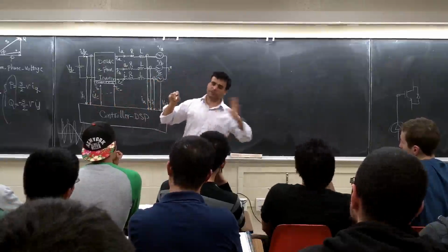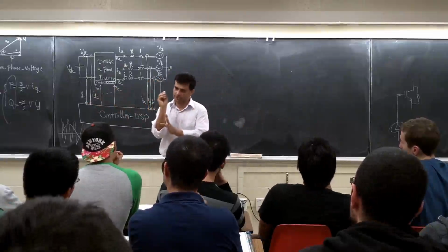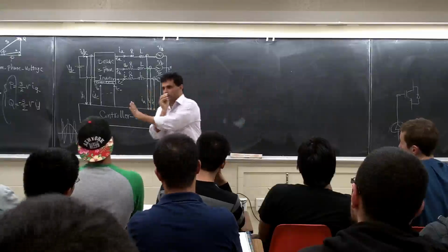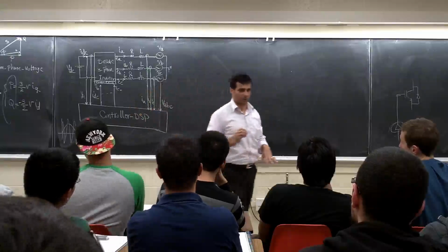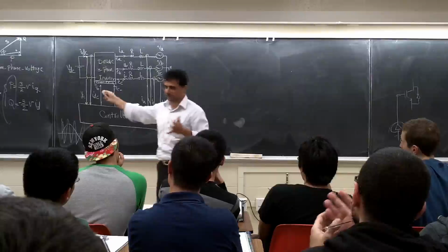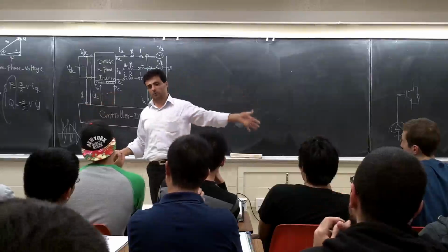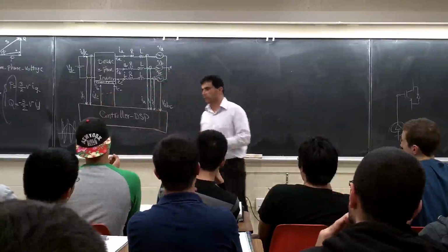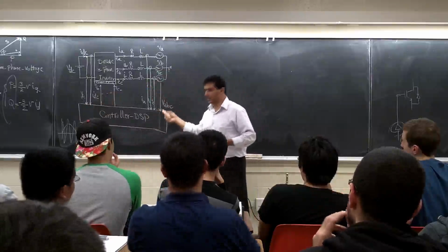Now, because when you know where you are on the grid, you can shift it this way and say, okay, I want to be here, or I want to be here. But in the project, I don't expect you guys to do that one. It's just manual. You set the grid phase to 0, and if you want 90 degrees, you can make the control minus 90 manually or plus 90. But this thing has to happen automatically in the system. And you need to have a PLL.